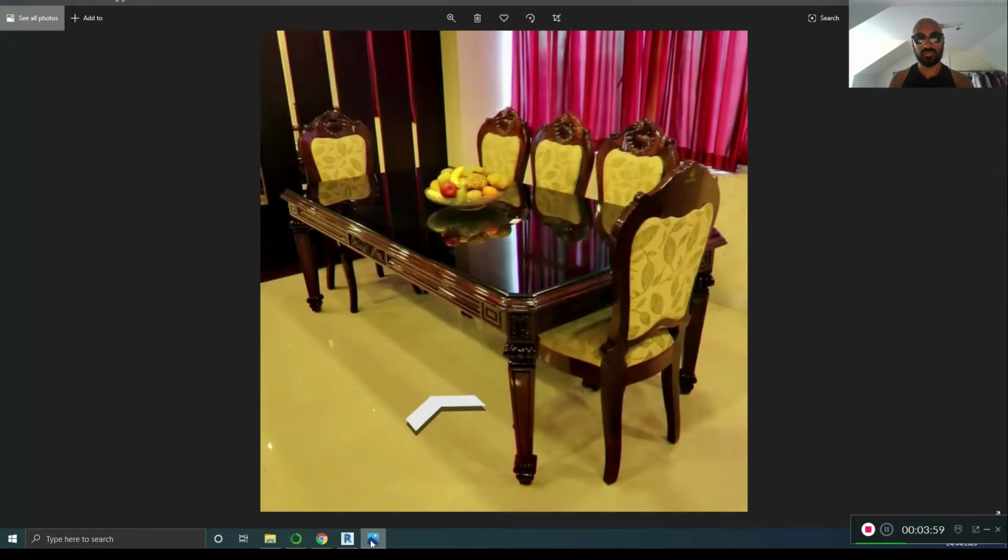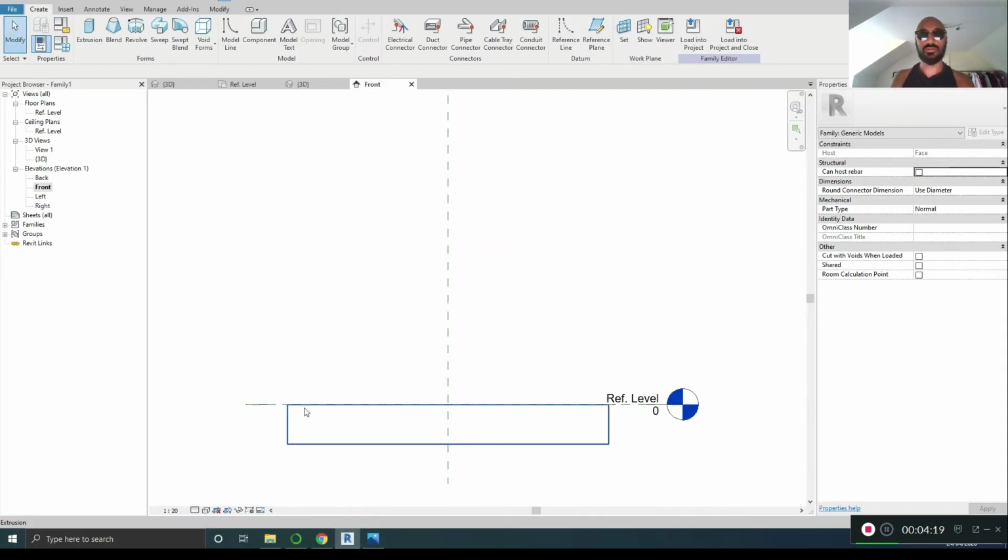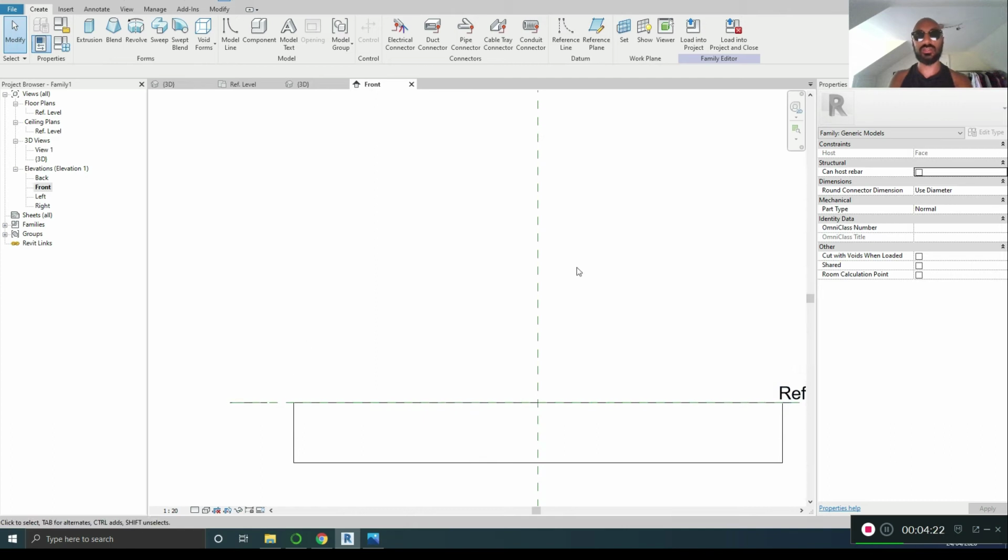So first thing we need to do is make reference planes. Always make reference planes. Get into the habit of using reference planes. Do not dimension to faces or model from faces. I've made a sofa video in the past where I did that, but that was when I was less experienced. You can make things that way, but they can't be changed later. We like to make things that we can change later.